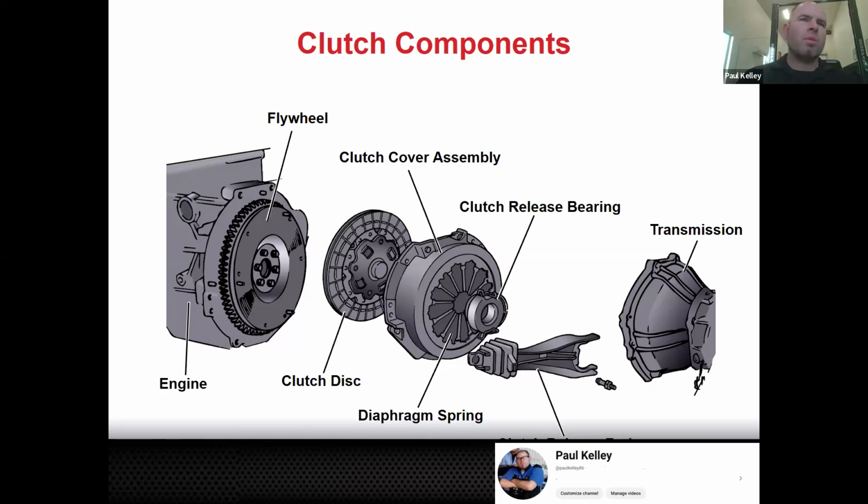You might get some issues though. The rotors may already be warped, and so you might replace the pads. Obviously, that's not going to address the pulsation, and the customer doesn't typically understand why the pulsation occurred. They just think it needs new brake pads, right? So similar with a clutch, a lot of our issues are not necessarily related to the disc. So it's best procedure to replace the clutch kit, which may or may not be available OEM. A lot of times from OEM, they want you to get individual parts and pieces.